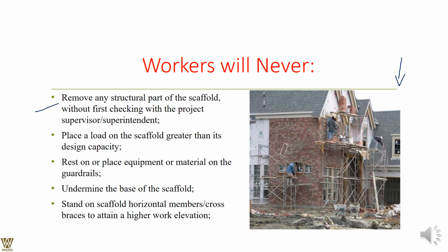Then comes placing a load on the scaffolding greater than the design capacity. Never do it, because it will ultimately lead to an accident. Over a period of time, with longer duration, the load carrying capacity will diminish and it will break down. So also, do not rest equipment or material on the guardrails.